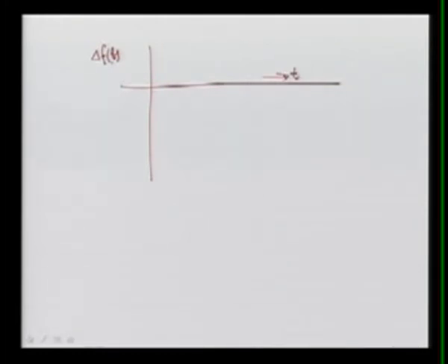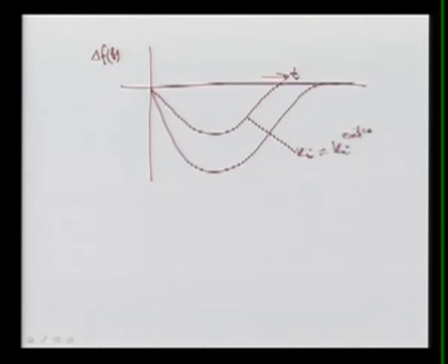So what we are going to get here, let's suppose this value is somewhere critical. Let's suppose this is Ki equal to the Ki critical value. Now as I said, if Ki is increasing, we are going to get an oscillatory response. So if this is the Ki critical, and you are still increasing from that, what will happen? You will get your oscillatory response, finally like this. So this is the change in Ki, as you keep increasing.